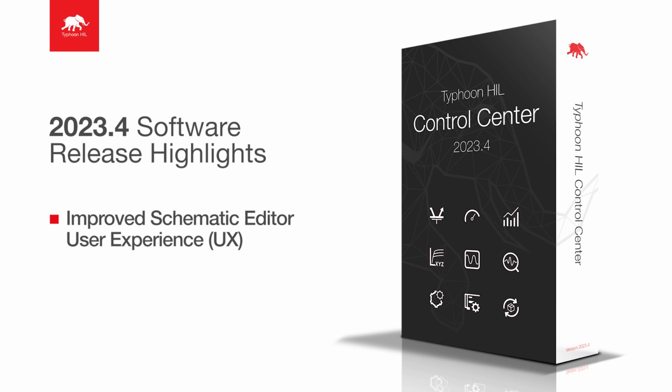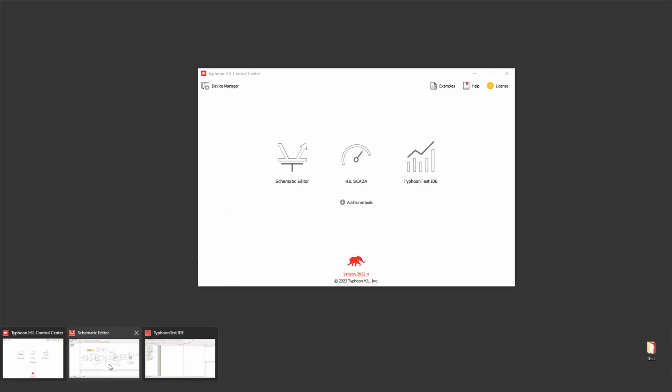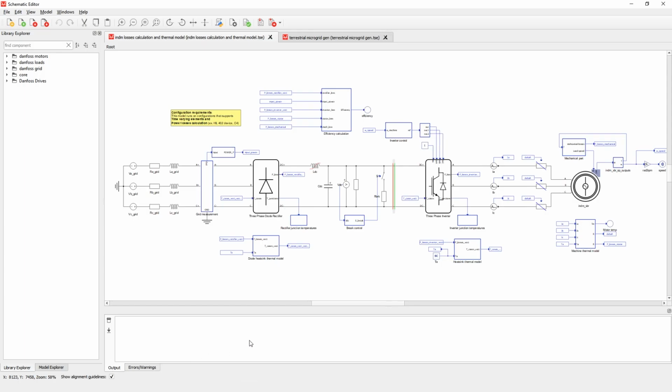Let's dive right in. One of the standout new features is the ability to generate a model building script from a selected part of your model. This feature lets you automatically generate an API for the chosen portion of your model, which can then be used in test automation scripts or component masks. Let's see how this can be done.